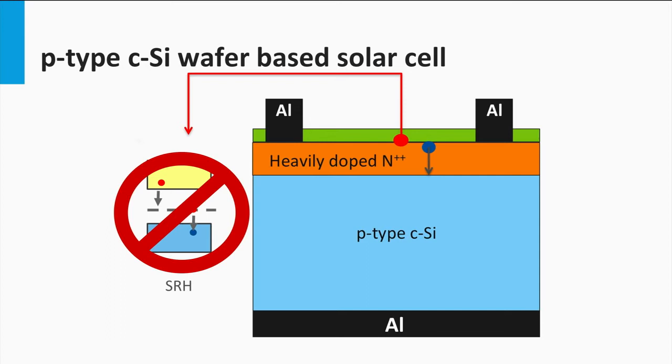In this case, the hole is indicated by the blue dot. Note that many charge carriers are generated by the bluish photons close to the surface. To utilize these light-excited minority charge carriers, the diffusion length of the holes has to be large enough to reach the depletion zone at the p-n junction, as indicated by the blue arrow. Increasing doping levels decreases the diffusion length of the minority holes in the emitter layer. Here you see an example in which the diffusion length has become so small that the minority charge carriers are unable to reach the p-n junction.